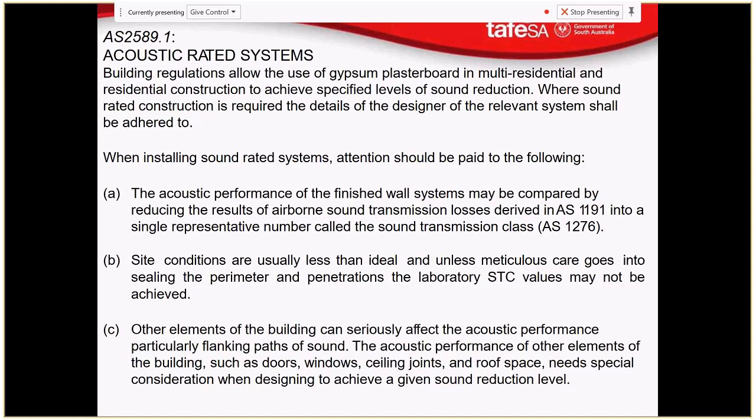Our measure of sound transmission is what's called an Rw value, and in the laboratory, this one stacks up to an Rw value of 50. It's called a DnTw value when measured outside the laboratory, but it only has to stack up to 45 when it's measured outside the laboratory. That's because that Australian standard accepts that something constructed in the laboratory does not always accurately match what we build on site.